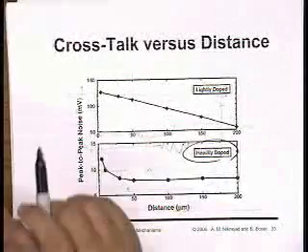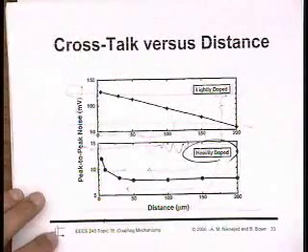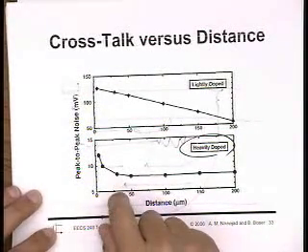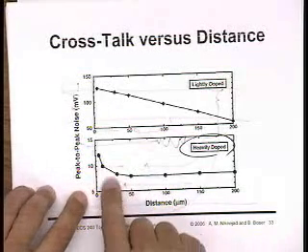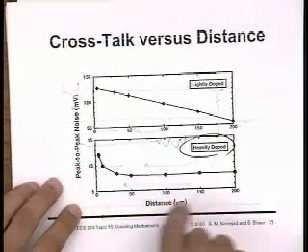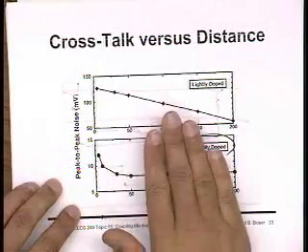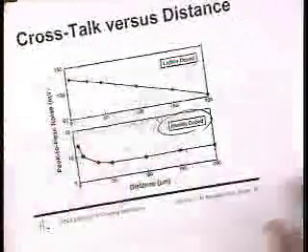All right, so that's actually one of the most important things to know, that if you have an epi substrate, then using distance for isolation really doesn't help you much. You know, there's a critical distance, so obviously you're not going to put a sensitive analog circuit 2 microns away from a noisy digital circuit, but for reasonable distances it doesn't really matter. But in a non-epi substrate, it does help to isolate things with distance.